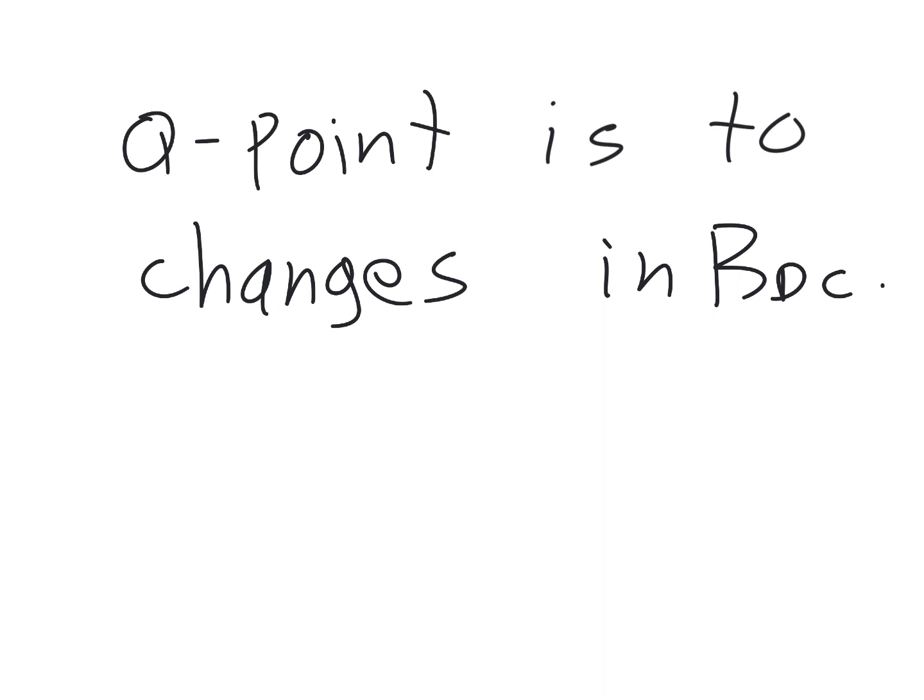And the beta will change. Just changes in temperature will cause the beta to change. So anyway, for a BJT, the two biasing methods that you'd use for an amplifier where a solid Q point is critically important are the voltage divider, which we're looking at the moment, and the emitter bias.